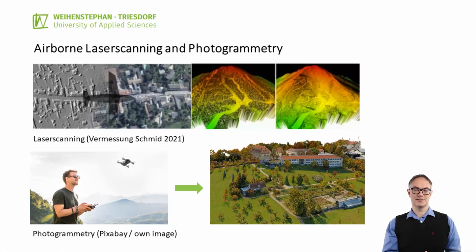Another cheaper way is through photogrammetry. If you're recording a video with a lot of images that overlap, the computer can relate these images to each other and identify identical points in these images. If you also know the exact location of at least one, better 4 or 5 of these points, it can be georeferenced and put into the context of a coordinate system. And the result is also a point cloud, even cheaper and faster than using a laser scanner, although not quite as precise.